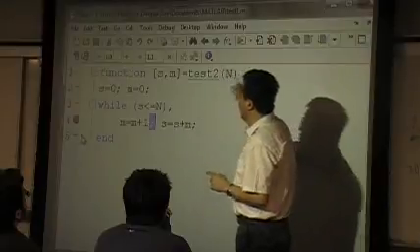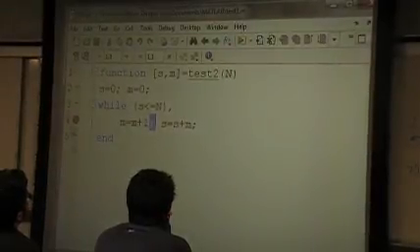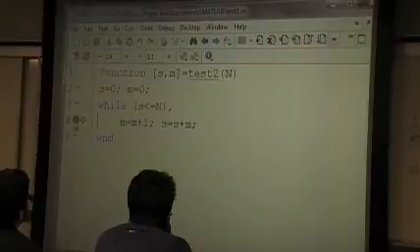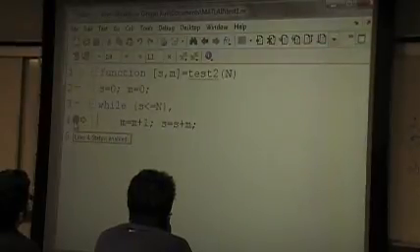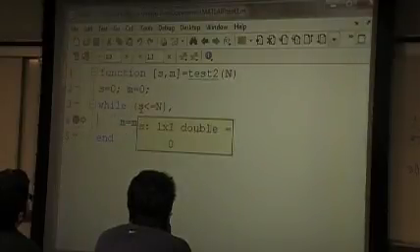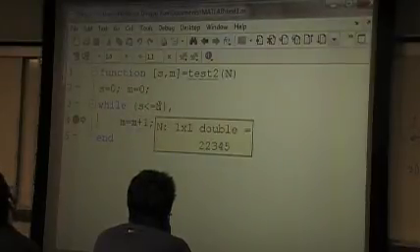And you can check the internal variables. You can set a breakpoint here, and then you can execute the function. And you see it stops at this point. If it stops, then if you move the cursor to a variable, it will display the value of the variable.